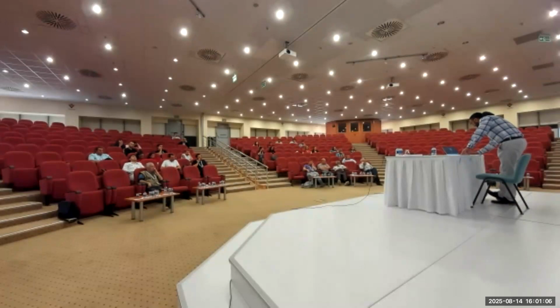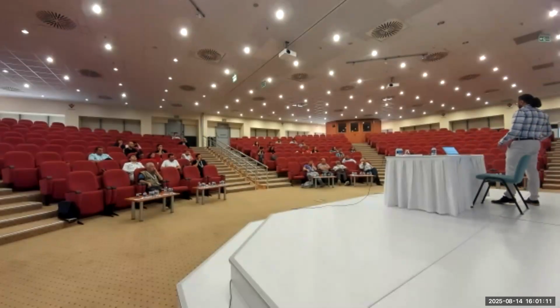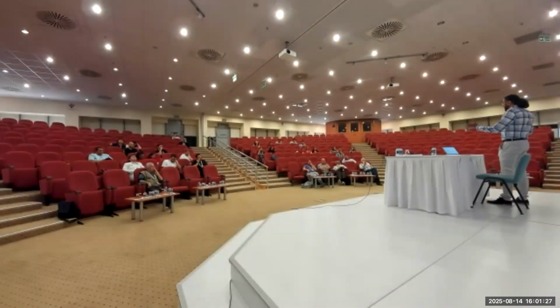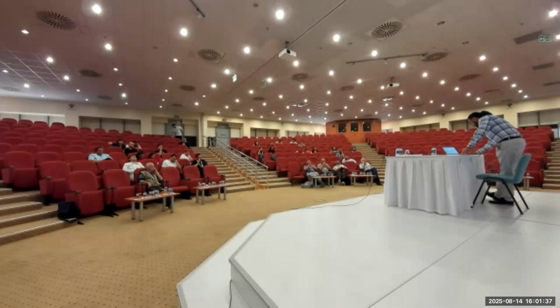Did you say the distance between the antenna and the bulbs is 1.5 meter? Yeah, 1.5 meter. Maybe we are in the far field. Yeah, maybe, but we are not at a good distance away. It depends on the antenna. For one of the antennas, we are not in the far field, and so we might measure the side lobes as well. But our neon bulb is not that big to capture side lobes of the antenna. So here, I think I have this here.